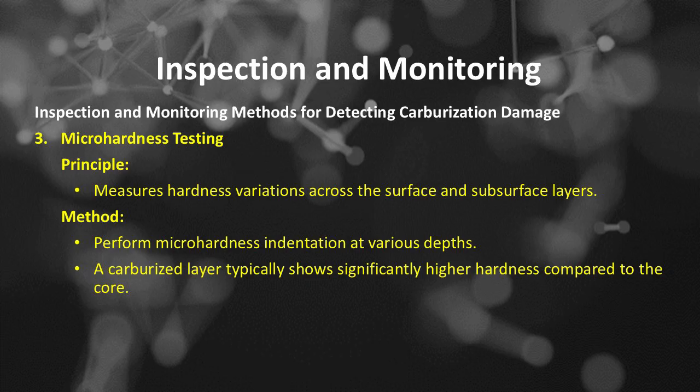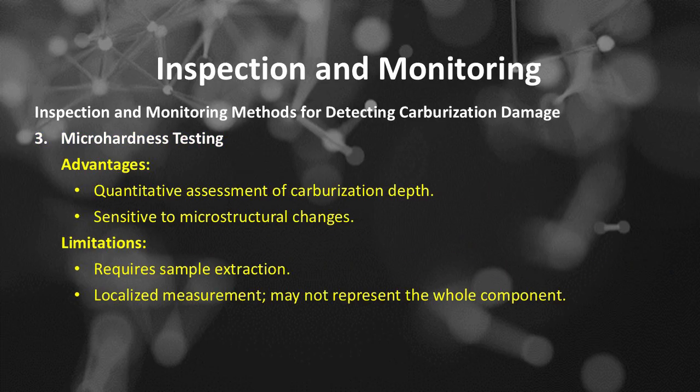Method of microhardness testing: perform microhardness indentation at various depths. A carburized layer typically shows significantly higher hardness compared to the core. Advantages of microhardness testing: quantitative assessment of carburization depth. Sensitive to microstructural changes. Limitations of microhardness testing: requires sample extraction. Localized measurement may not represent the whole component.